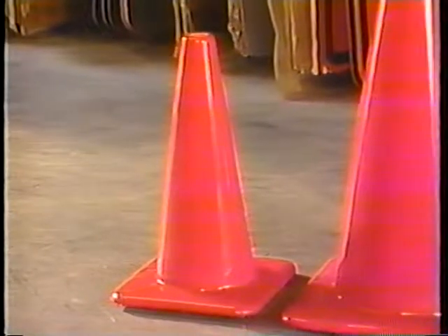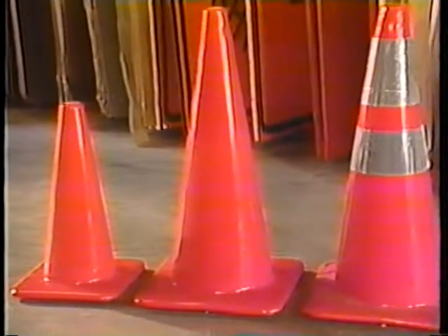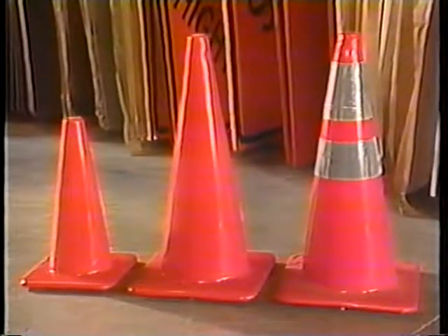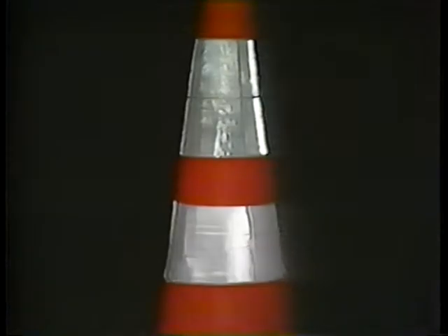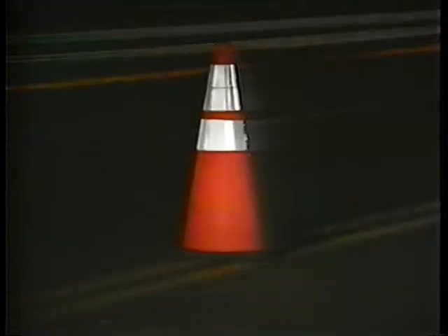Cones cause little or no damage when hit. They must be at least 18 inches high, but 28-inch cones must be used on freeways and other roadways where speeds are 45 miles an hour or greater. At night, 28-inch cones or larger must be used. 28-inch cones must have a 4-inch wide band, 2 inches below a 6-inch band. Any cone height less than 28 inches is not acceptable for nighttime use.